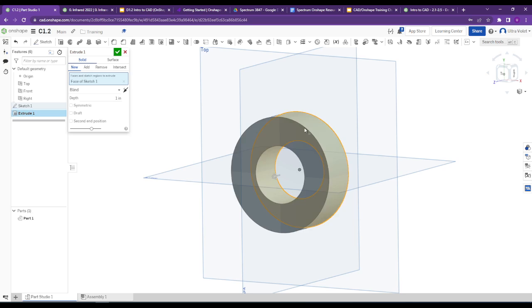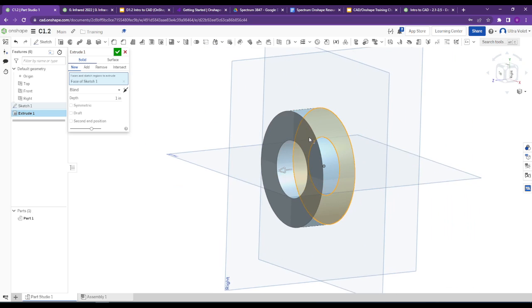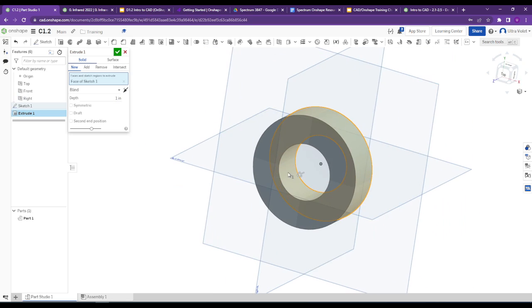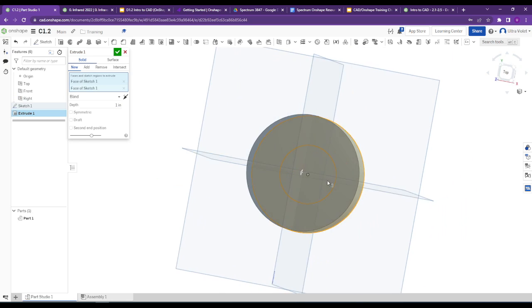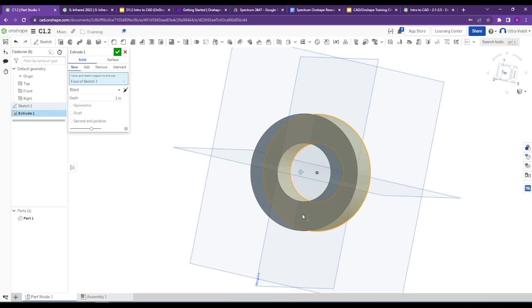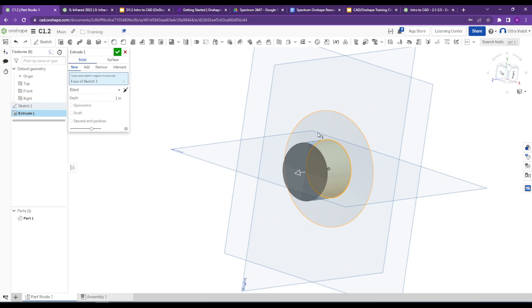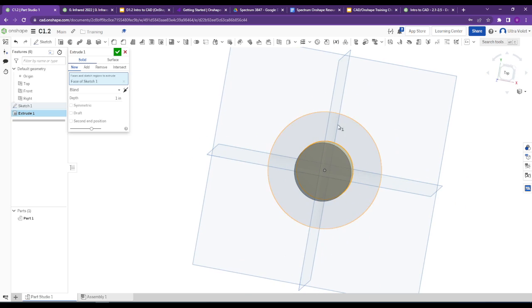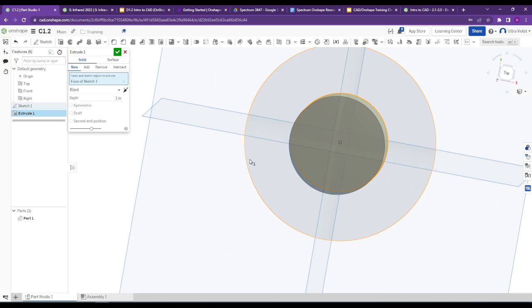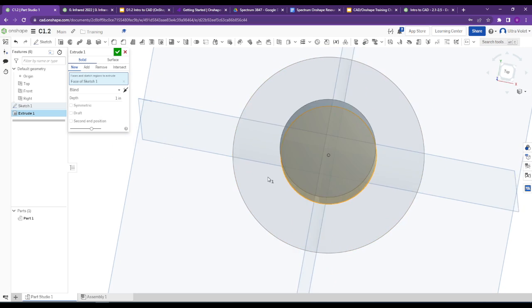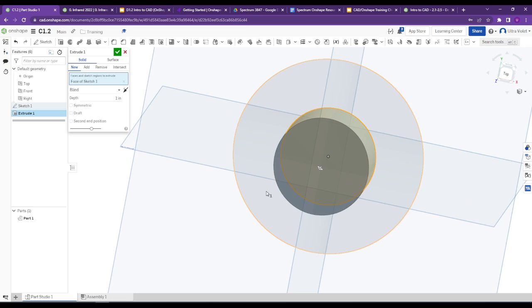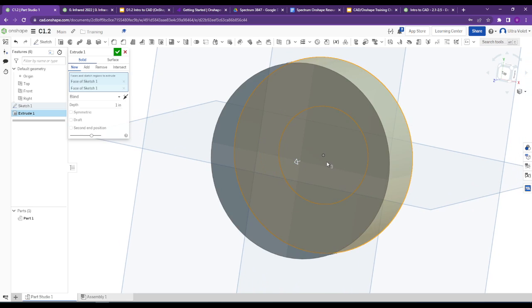So I can click on this outer ring and make it a certain thickness that way. You can also click on the inner ring, so I can make the whole loop there. You can click on just the inner part. So anything that is a closed section of the sketch, right? It has the 2 circles, there's no line breaks or anything, it's a fully closed shape. You can do different extrudes on it if you want.